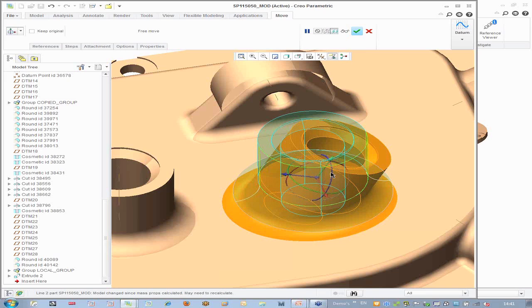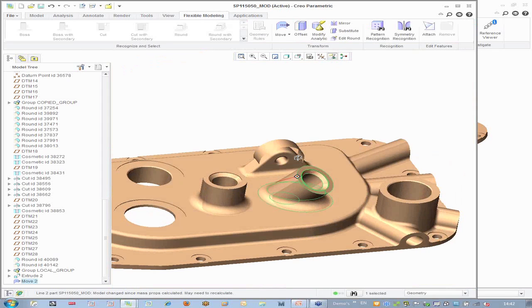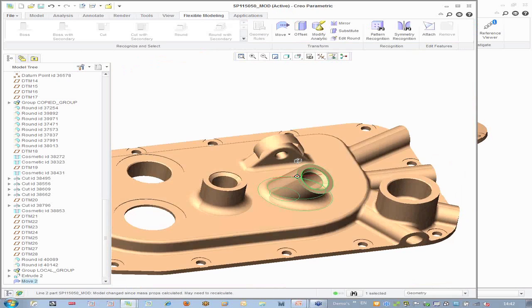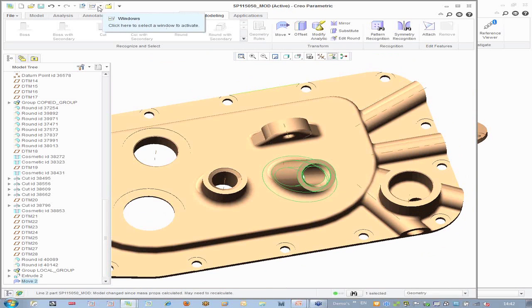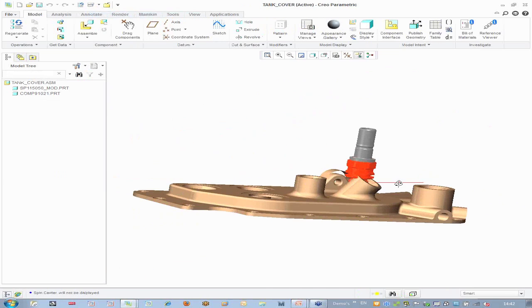I could go back and revisit this later on and build dimensions if I see fit, but I haven't had to worry about that during the design review, where we're just interested in changing the geometry so that we've got a new concept. So again, what's happened to the existing assembly? Well, if I was adding features here, then that assembly would fail, because it wouldn't know where to put this boss.